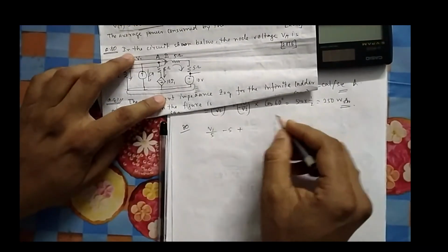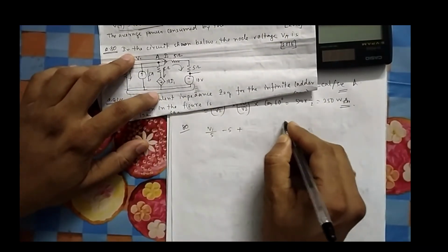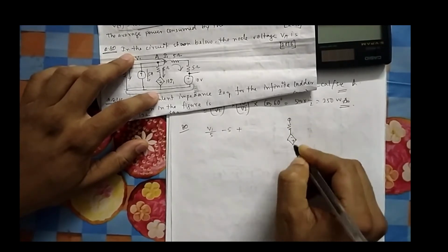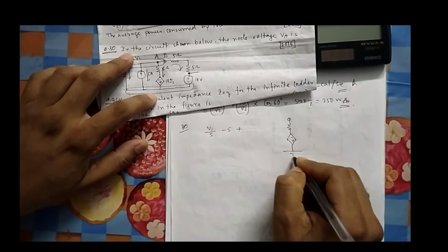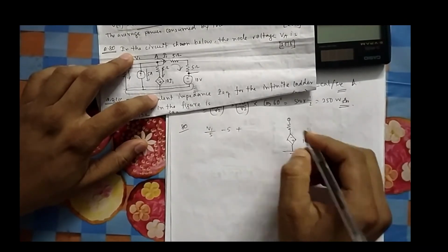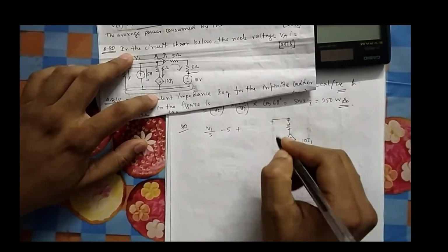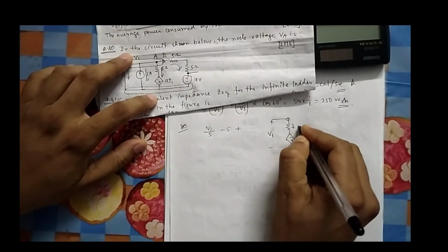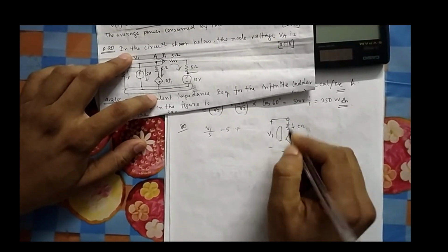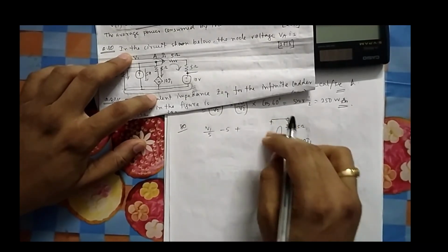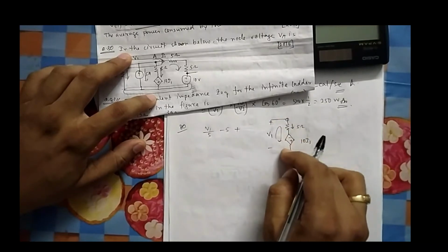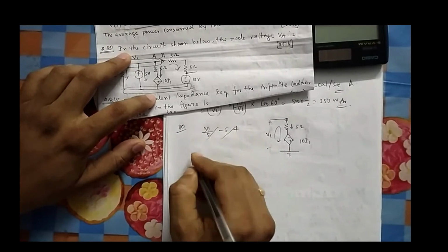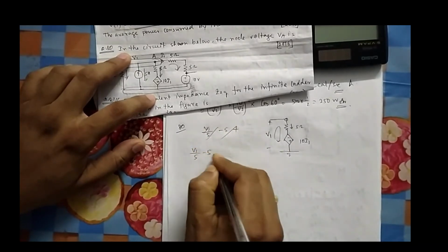Suppose I have V1 here. Let me draw it here so that you understand from where it is coming, and this is my ground path. So this is 10 I1 voltage, and this voltage we have considered V1. And this current we are interested in, this is 5 ohm. So you can take KVL in this path, including this V1, so it becomes a complete closed path. I will move to this and I will return through V1. So if you take simple KVL here, you will find where this answer is coming from.